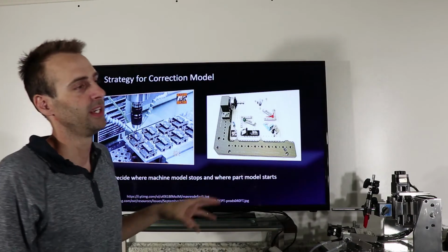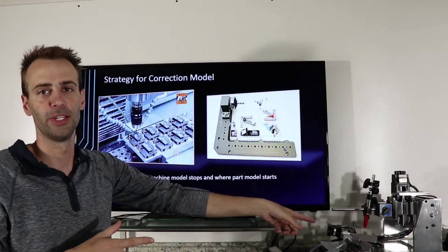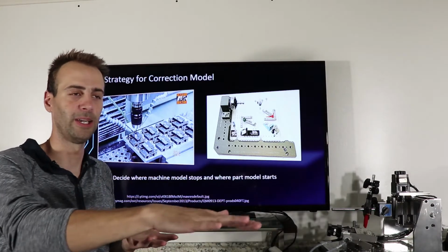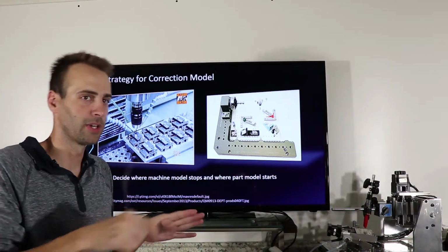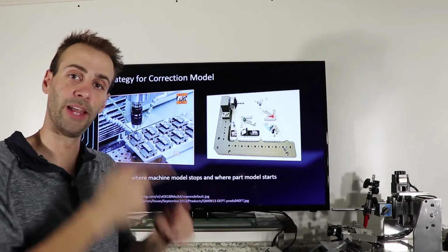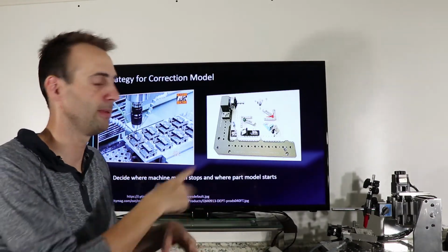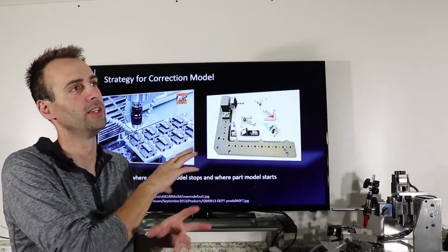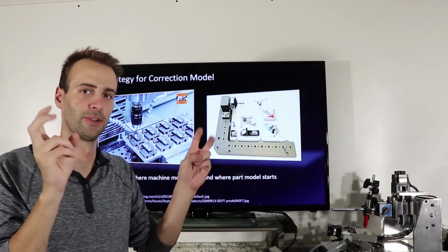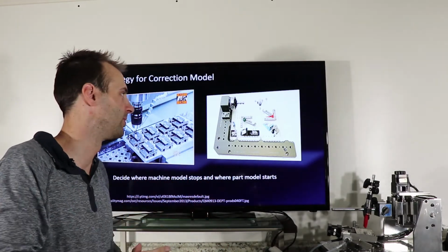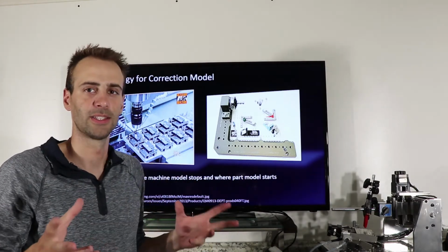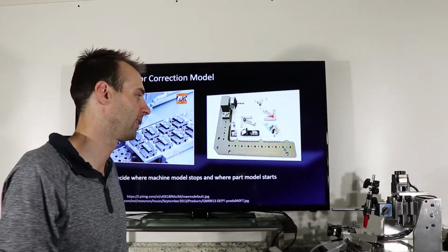So in summary, if you have a CNC 3020 like what's sitting here, there's no vise at all, it's just a flat bed. Well, scribe a line there, put a sphere, drill a little tiny hole, and call that the origin of the machine always. Or maybe you have home and limit switches so you can run it to home, and the position it sits in at home is the zero point of the machine. The problem with doing that is even though homing switches are nice, they're not really as repeatable as you think they are.